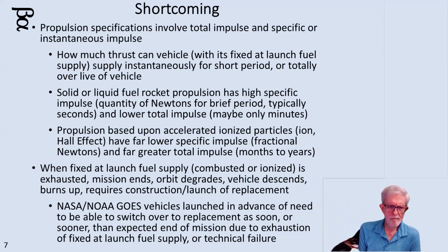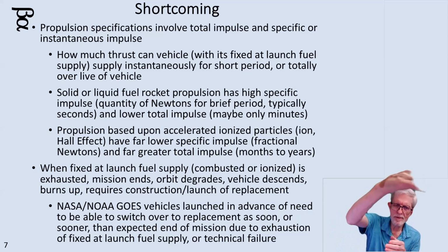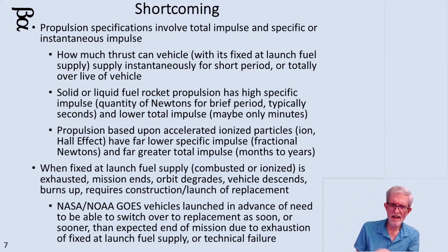But how do they do that with the big satellites? Well, if it's a critical satellite like a weather satellite that just always has to be there, they'll put them out with backups. So you might find, like, the GOES satellites. When the GOES satellites go up there, a couple of years after one gets up there, they launch another one. And they put it into a parking orbit not too far from where it would normally be. So when they have a problem or it starts running towards low fuel, they take the active satellite and they shove it over to the Pacific, and they bring the other one in from the edge of the Pacific into that same station. So you have a replacement process for GOES satellites. And that's how they deal with it. They do run out of fuel, and once they run out of fuel, they tend to drift plus and minus that station keeping orbit over the Pacific.